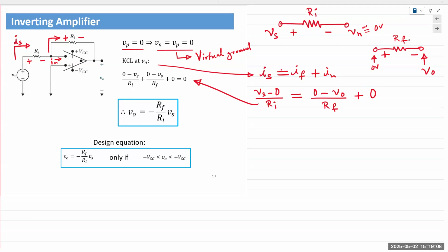So the question being asked is if there is a resistor at the V out terminal, then yeah, we'd have to take that into account. But for most intents and purposes, if you're trying to just find V out, then we can simply take just RF and Rin, irrespective of what is connected at V out. So for this circuit, we won't take into account V out at all.